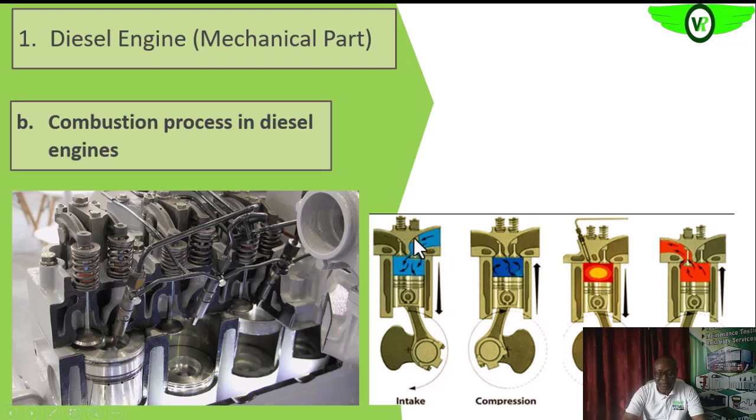So that reduced pressure will cause air to push in, since the pressure outside is higher, as expected. Although the rocker arm movement is what, as we explained earlier, causes this movement of the valve. So the valve will open, the rocker arm, you see it's depressed. The rocker arm will push the valve to open, the intake valve.